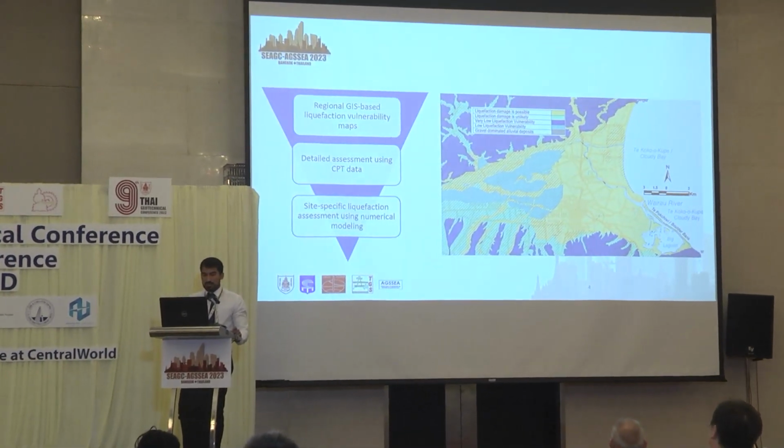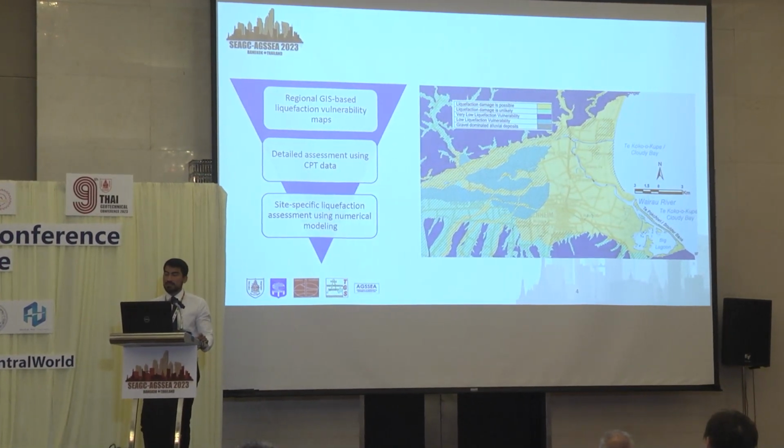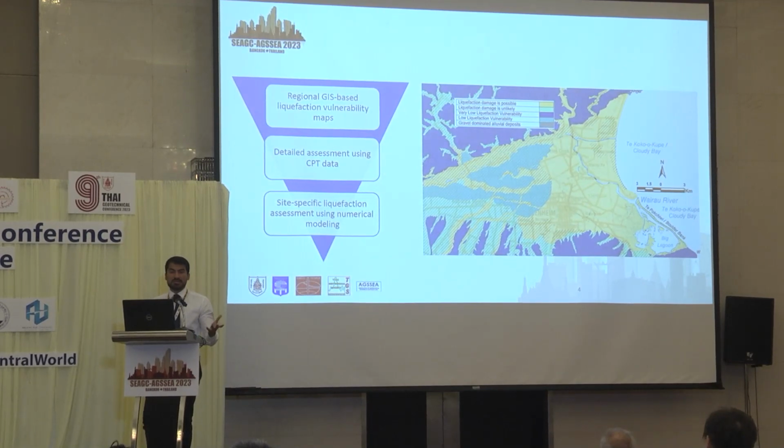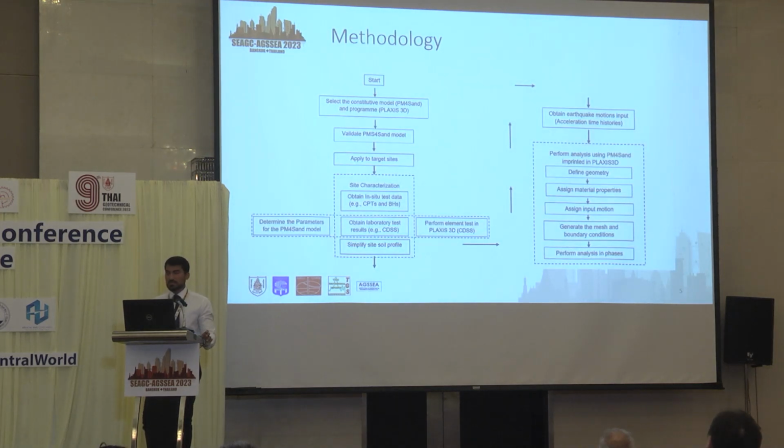The second step I performed was getting the CPT data available in the New Zealand Geotechnical Database. It is collected from all over the different projects. We also performed some new tests, which were dynamic probing tests, as CPT is not possible in gravelly soils, and some analysis was done. Then it leads to the third part, which is the numerical simulation using effective stress analysis, and that I will explain in a bit more detail in this paper. This was the methodology adopted to perform the numerical simulations.